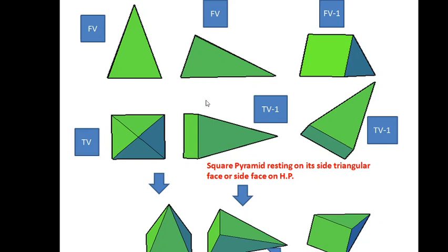If you observe in the top view, the base is visible. If we consider the 3D model here, I can observe the base very clearly. So in the top view, the base will be visible, and the top edges, edge number 1 and edge number 2, will be very clearly observed from the top side. The bottom edge number 1 will be a dotted line here, and a dotted line from this point to the apex. The same thing we have to redraw here.